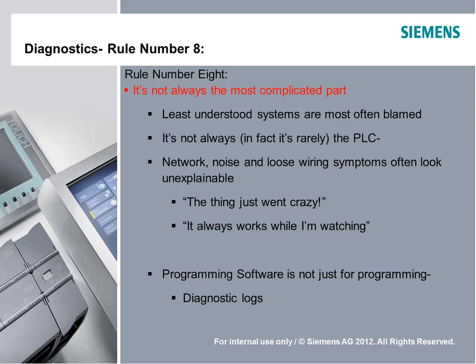So loose wiring, I/O modules, that kind of stuff is much more prevalent when we look at faults, because the PLC is typically sitting inside of a nice enclosure, usually with the door closed and temperature controlled or whatever. Not always, but usually. Where the rubber meets the road is actually through the I/O. So in other words, we can have I/O cards that are right there in the PLC rack, but the wiring goes outside into the real world, and that's where things like arc welders are going on and forklifts running over conduits and all that kind of stuff. So the I/O is much more likely to be faulting.